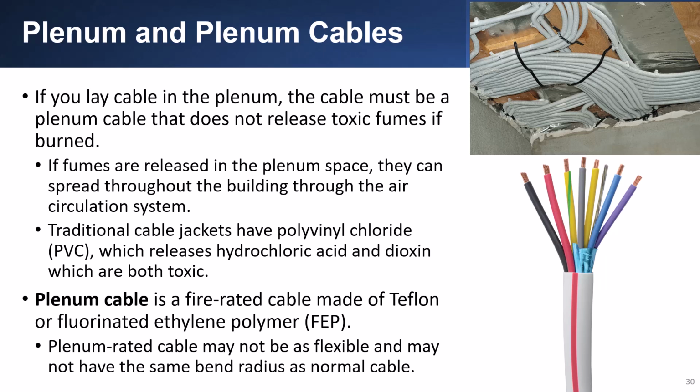Traditional cable jackets have polyvinyl chloride, or PVC, which releases hydrochloric acid and dioxin, which are both toxic. Plenum cable is a fire-rated cable made of Teflon or fluorinated ethylene polymer, or FEP. Plenum-rated cables may not be as flexible and may not have the same bend radius as normal cable.